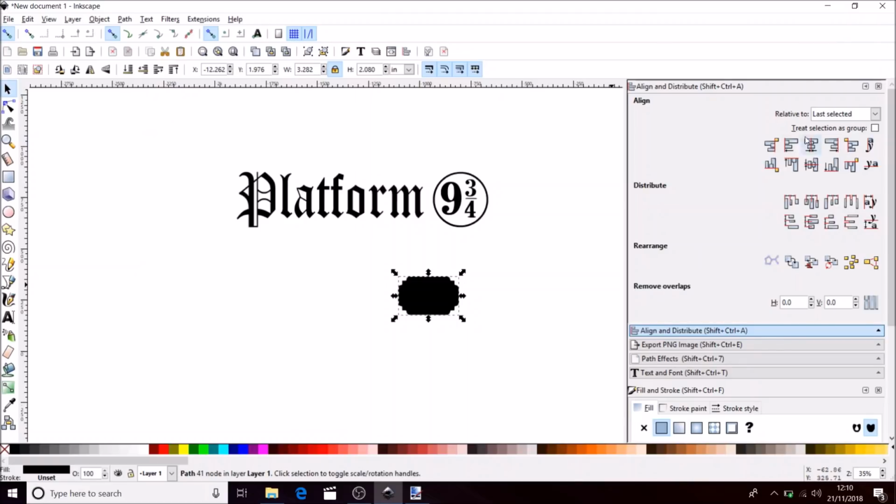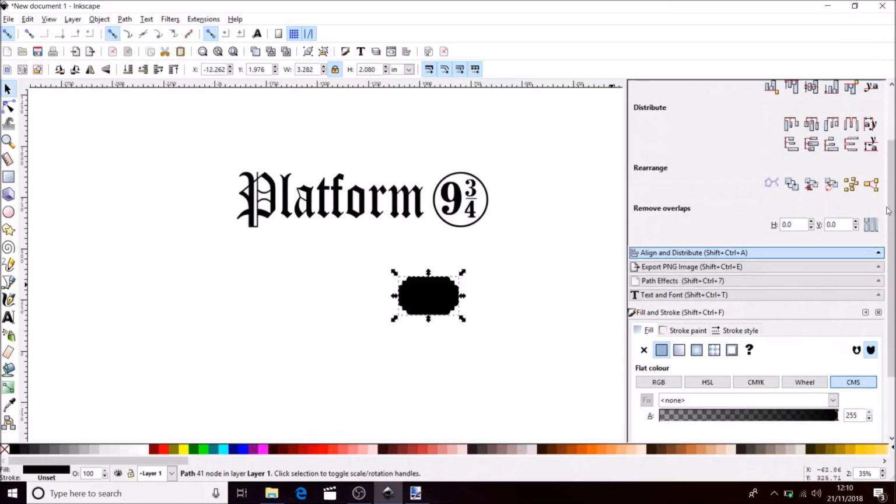So coming again to the menu on the right hand side, the title said Fill and Stroke. So I'm going to come onto Stroke, click on that one. I want to turn the stroke on. You can choose any of these ones, but I'm going to go for this box. What this is, it's going to do an outline on the sign. So that's clicked on, and I'm going to go on to the next button there, fill. Click on that. I'm going to turn that off. The fill is the color inside the box, so I'm going to get rid of that.